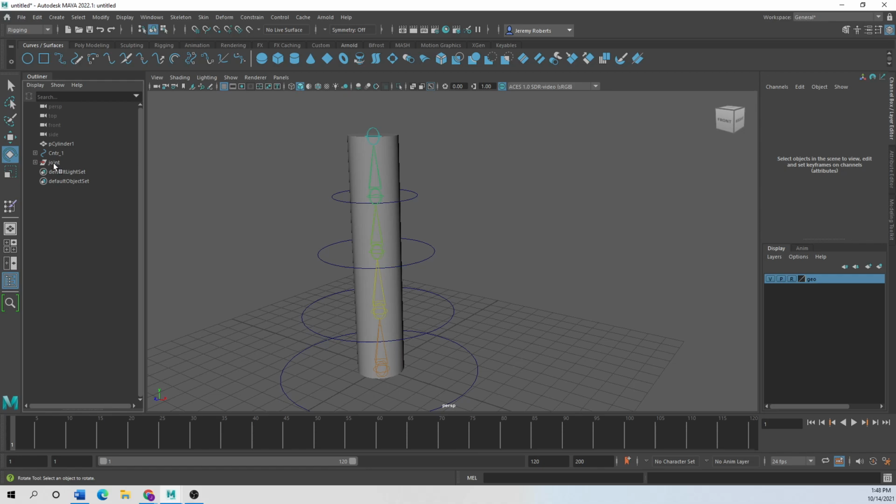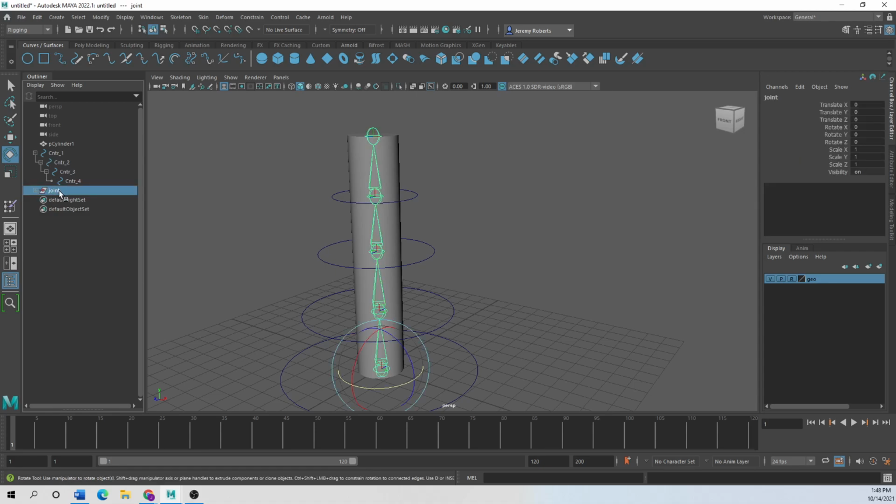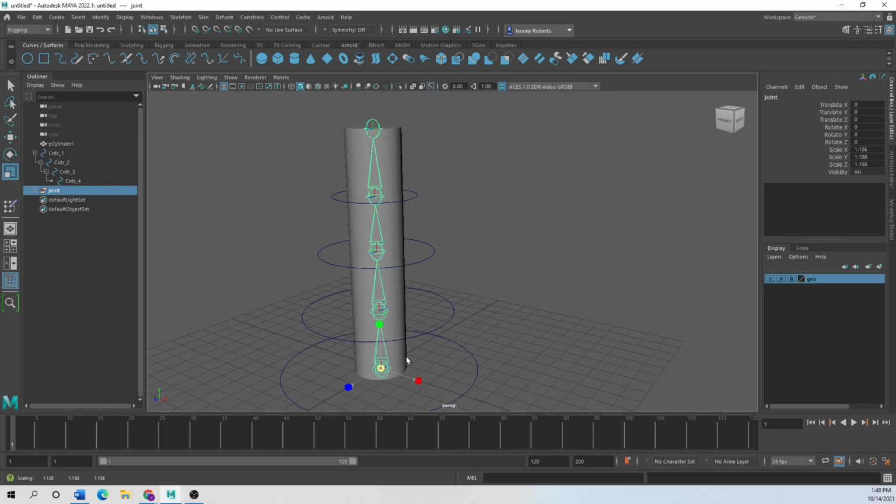Basically, you don't want to touch it. You can put labels on here saying something like animator, don't touch this, however you want to do it. The only thing you're going to be messing with when you're animating is these controllers right here. But what you can do with these groupings is lock stuff out. Say I don't want to adjust the scale of these things at all.